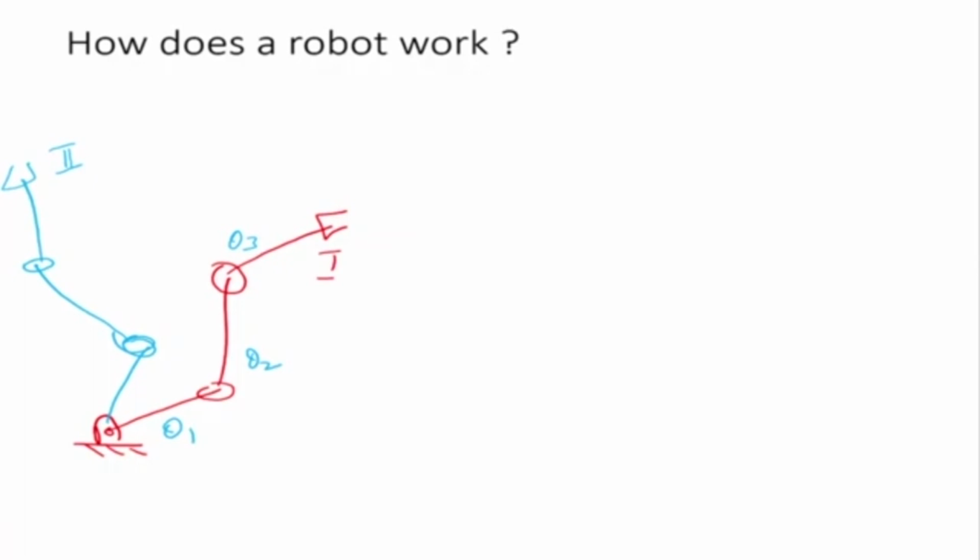So what the controller basically does is it finds out the difference between the present and target values: theta 1 dash here, theta 2 dash here, and theta 3 dash there. So it is theta 1 dash minus theta 1. It generates an error, and then drives this error towards 0. So now basically what we are seeing is that for the controller to function,